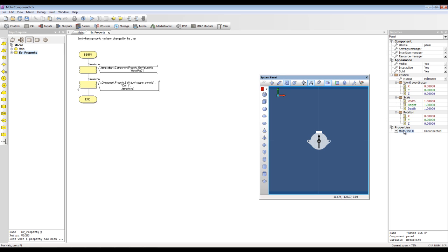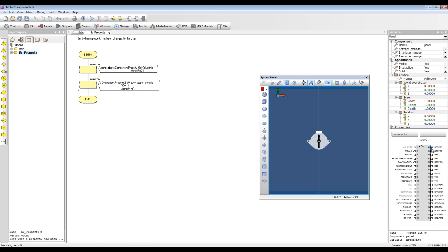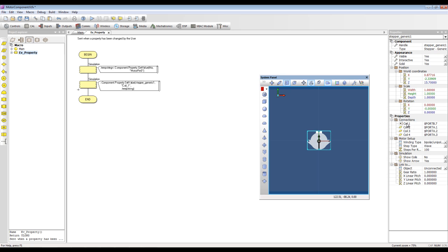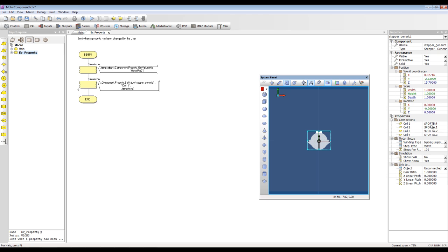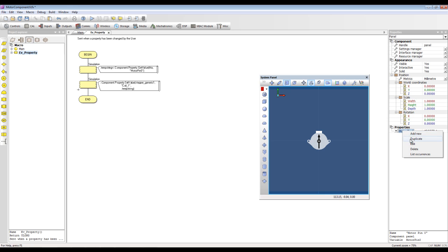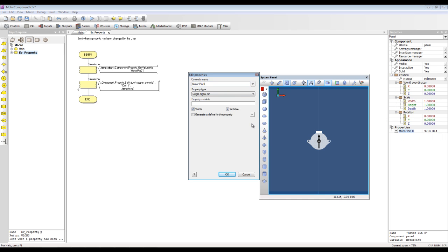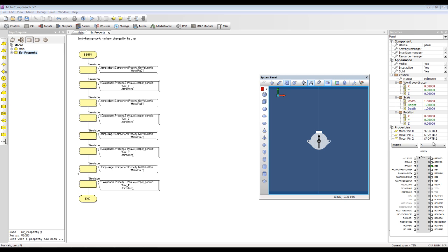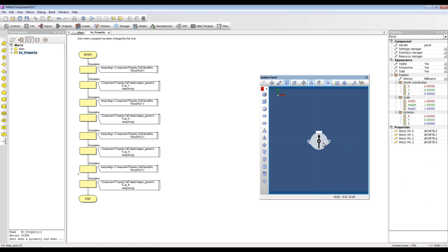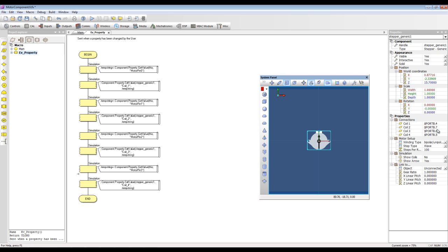And you can see that if I take this motor pin 0 and connect it to a pin, RB7, it's connected coil 1 to RB7. Just to prove I'm not lying, RB4 is connected to RB4. So what I can do now is duplicate via the right click menu, it's motor pin 1. So here we have all 4 pins set up, and now when I set the value here, so RB5, it should copy all the pins across to the motor component.